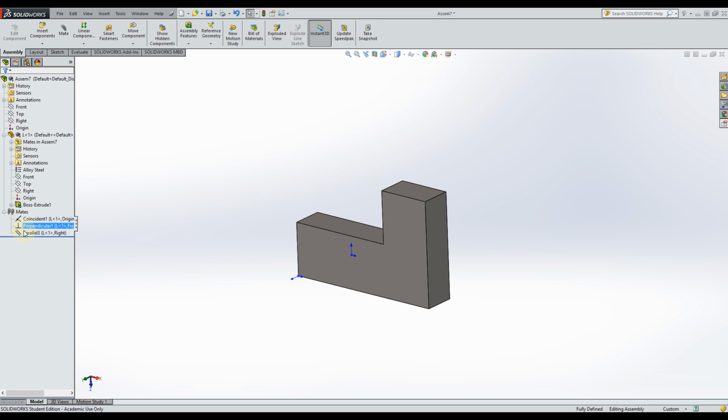So if you want to change the axis systems from the part to the origin, it requires you to fiddle around with mating all the main planes of your assembly in your main part. Okay, so this is one section of the part. Now we'll continue to creating multiple configurations and show you how configurations work in both the part and the assembly environment.